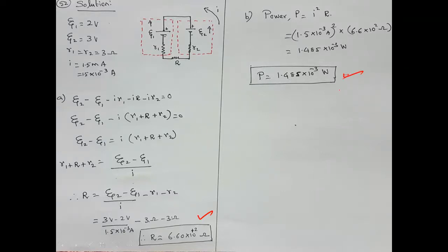So, my dear, in this way, you have to apply the rule very carefully. First of all, the circuit should be closed, and the second thing, you must identify what is your battery power. If the battery has the highest value, then you have to give importance to the highest value of the battery, and you have to consider the direction of the current from that battery. Clear? In this question, our second battery is the strongest one, so I consider the direction of the current from the second battery. Clear, my dear?